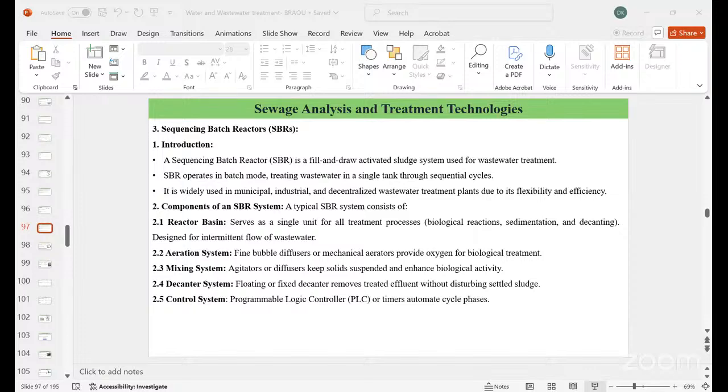And coming to the advanced oxidation process, this is another process apart from membrane filtration. These AOPs are generally a chemical treatment procedure designed to remove organics from the water and wastewater by the process of oxidation through several reactions with OH radicals and other strong oxidizing species.